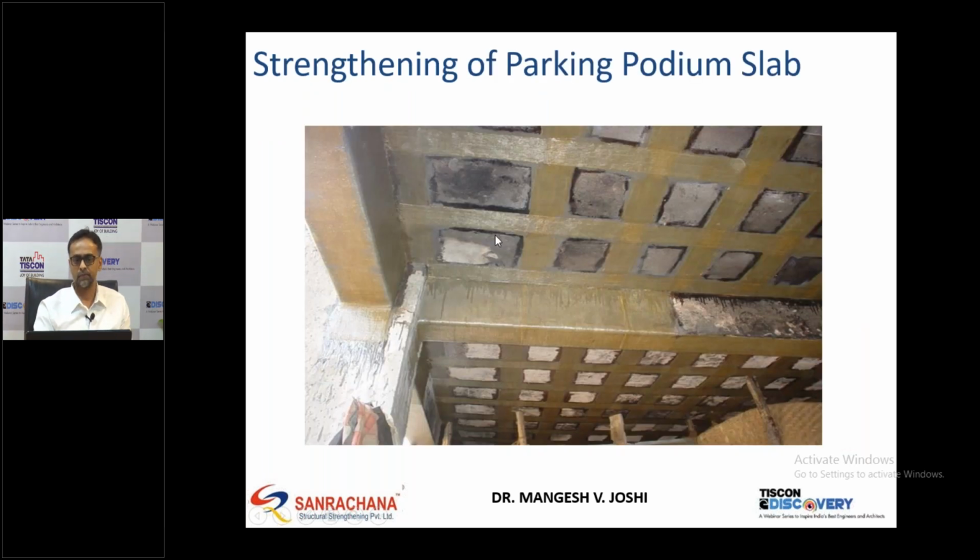Then this is for a podium slab. In this particular case, there was a change in use. The client got additional FSI, so he put some additional four floors on top, and he converted the first floor into podium parking. Naturally, this podium parking was not designed for vehicular load, but only for normal live load. It was a two-way slab, so we wrapped in both ways, X and Y. Beams were naturally failing in shear, so we strengthened the beams in the shear zone as well as in the flexural zone.